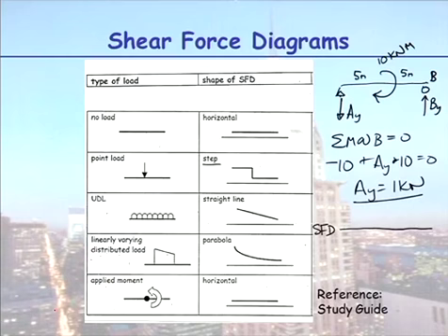Again, you don't panic. I follow my loads. I step down 1. My shear force diagram is a plot of vertical forces. Is my moment a vertical force? No. I step down 1, I move across, and I step up 1. So whenever you have an applied moment here, nothing happens in your shear force diagram because you are plotting vertical forces in your shear force diagram.